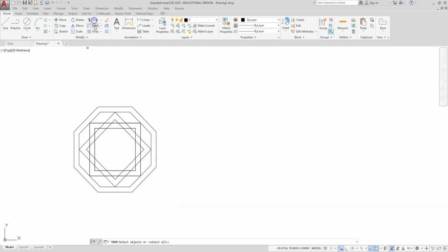There we go. Go to trim, hit the enter button, and now as we point to the objects, we can pay attention to where that X pops up, and if you see the X pop up, then that means it's trimmable. Looks like I have multiple squares under there, so I need to erase those. So back to trim, hit enter, and go through and just look at what needs to stay and what needs to go away, and then work your way all the way around and trim up this